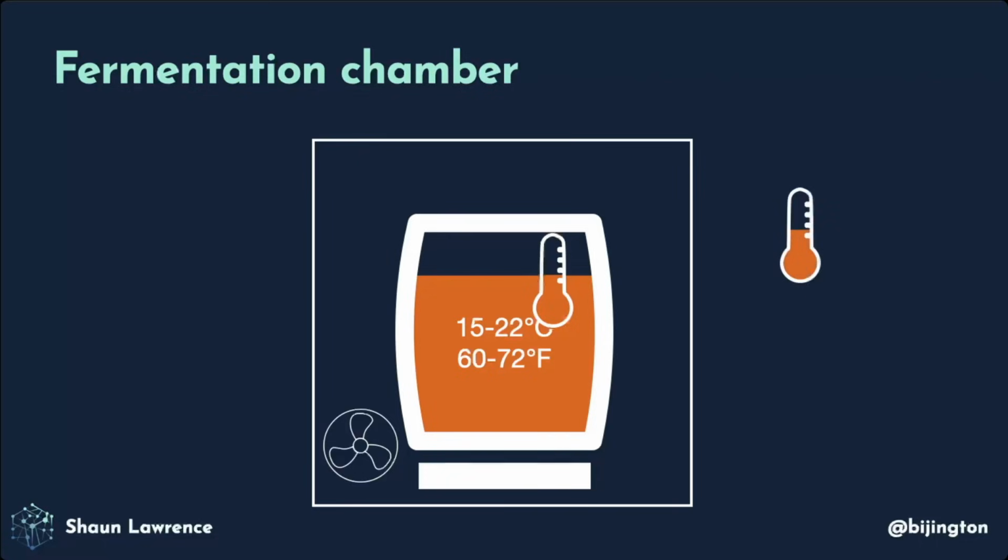And then finally, I've opted to measure the ambient temperature. The main reason for this is if you know it's 10 degrees outside and you're heating, you know that if you overshoot, the temperature will naturally drop. You don't have to turn on the cooling element in order to come back down.